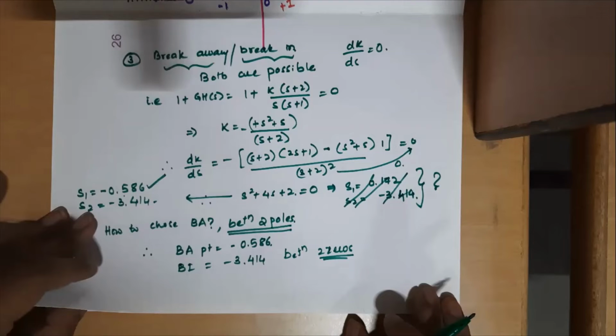You take the characteristic equation, rearrange everything in terms of s, and for those equations you go on substituting k equal to 0, 1, 2, 3, 4, say up to 10 to 15 values. For every s1, s2, s3, you go on marking in the s plane. Then later join all those points. You will definitely get this shape of root locus. There is no doubt.